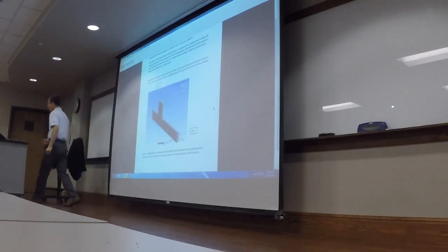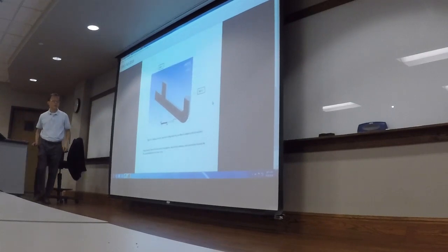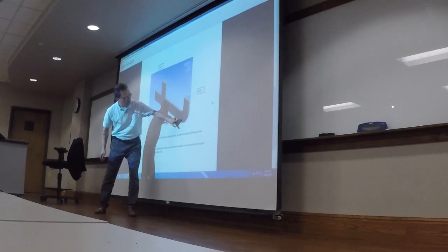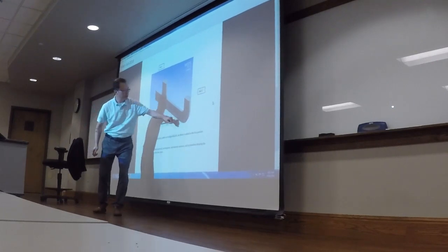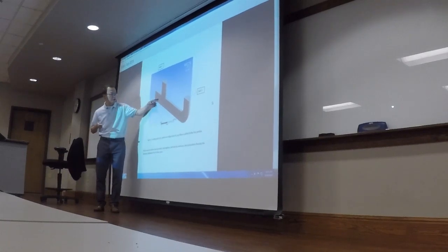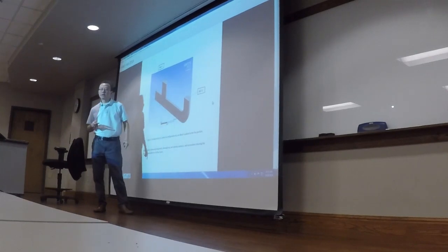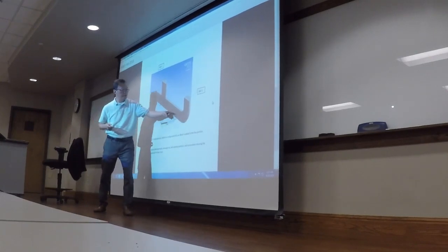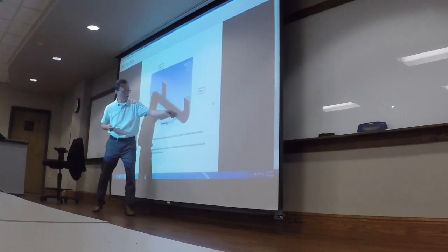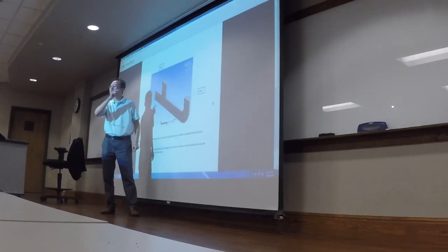That's configuration number 1. Configuration number 2, a little more complicated. Same thing. Let's create that YZ plane. Let's create a new plane, and just like the tutorial, let's create this profile. This is called a profile, and this is the path. So let's create a straight line, which is 12 inches long. Then here we'll arc by center.